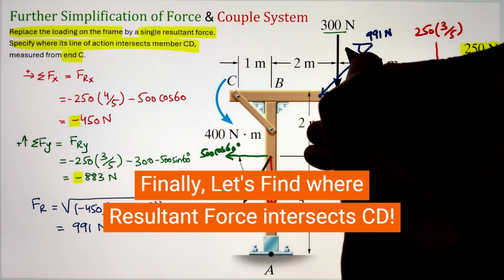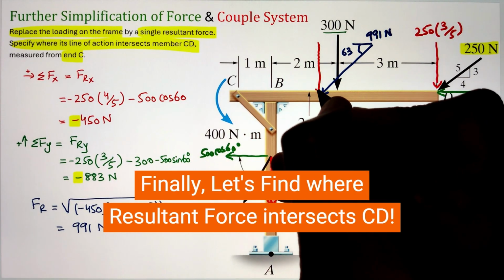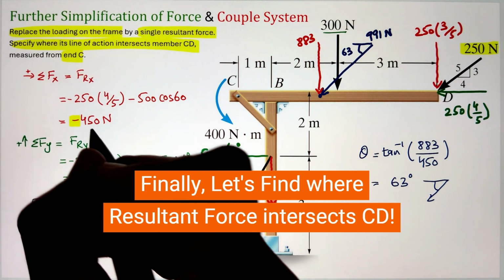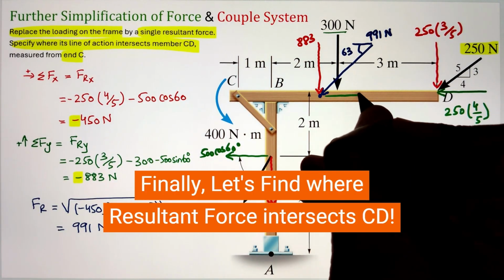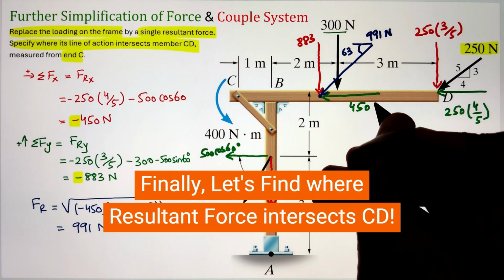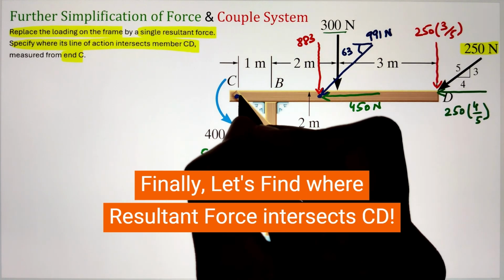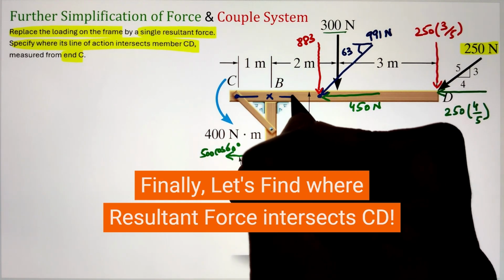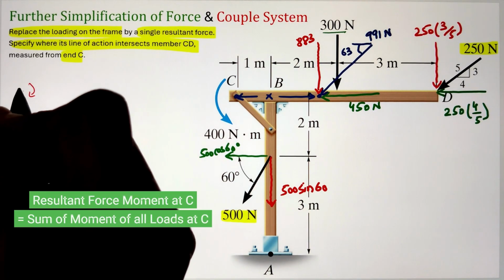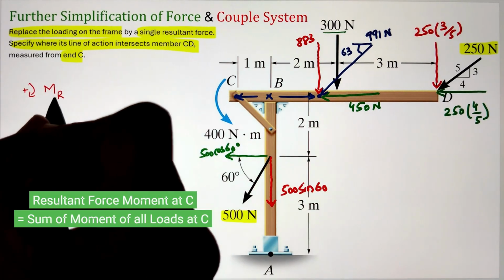Next, we can go ahead and represent our force and its component on the beam in order to identify its position with respect to point C. So let's go ahead and identify that position x. To do that, we will utilize our summation of moment formula. That is the summation of moment of the resultant force component at point C will be equal to the summation of moment of all the individual loadings at point C.